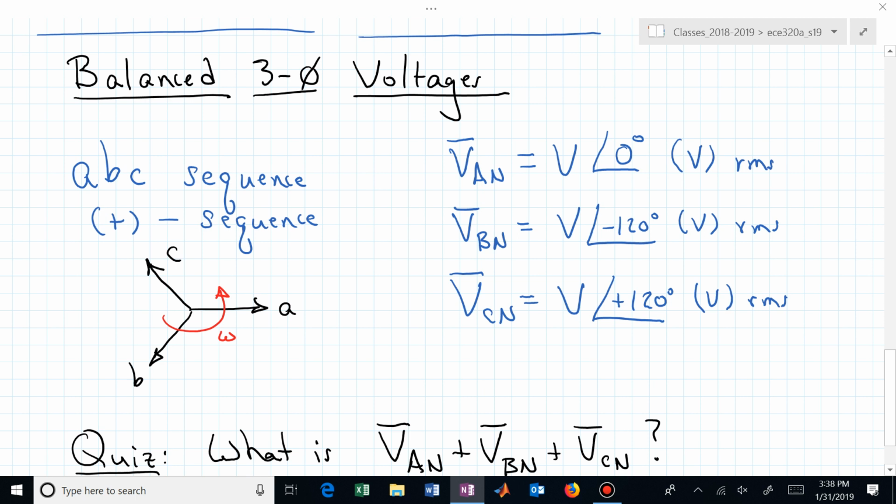But that's what I'm meaning by this phasor, and a lot of times this rotation of those phasors is not even acknowledged or written down, but it's there and it's doing it at a frequency omega, which for power problems in the United States is usually close to 377. 2 pi times 60. If that's the case, then if we use our A phase voltage as the reference, then we simply change the B phase and C phase by the appropriate phase shift of 120 degrees relative to ABC in this positive phase sequence discussion.